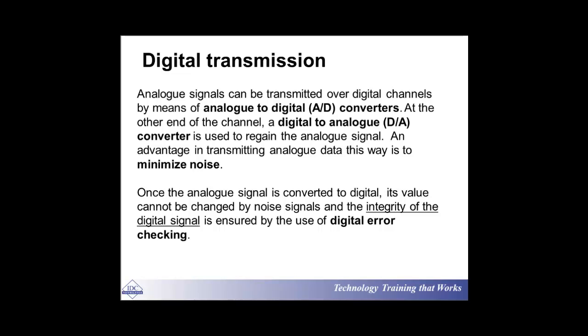But when it comes into the SCADA RTU or SCADA PLC, these signals need to be digitized. So you need to have analog to digital converters. And then again, by the time it is processed and analyzed, the information has to be sent back to the field devices just to adjust themselves, okay?